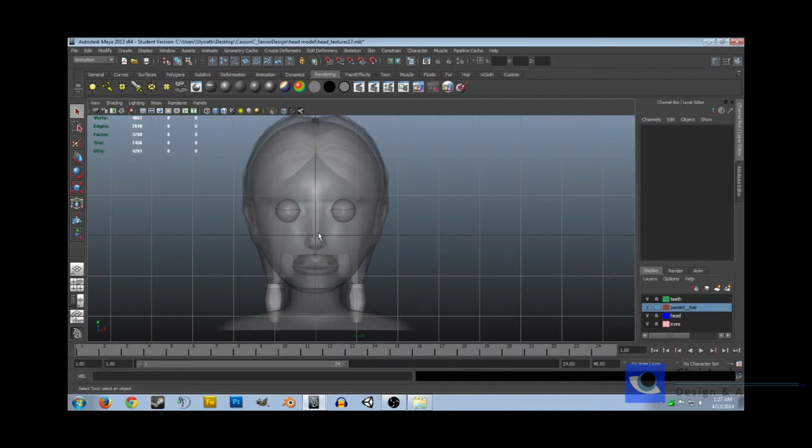Start by going to Skeleton, and then select the Joint tool in the main menu bar above. If that option is not there, then go to the pull-down menu on the upper left corner and select Animation so that the option appears. We will create a joint at the base here to represent the start of our character's spine.